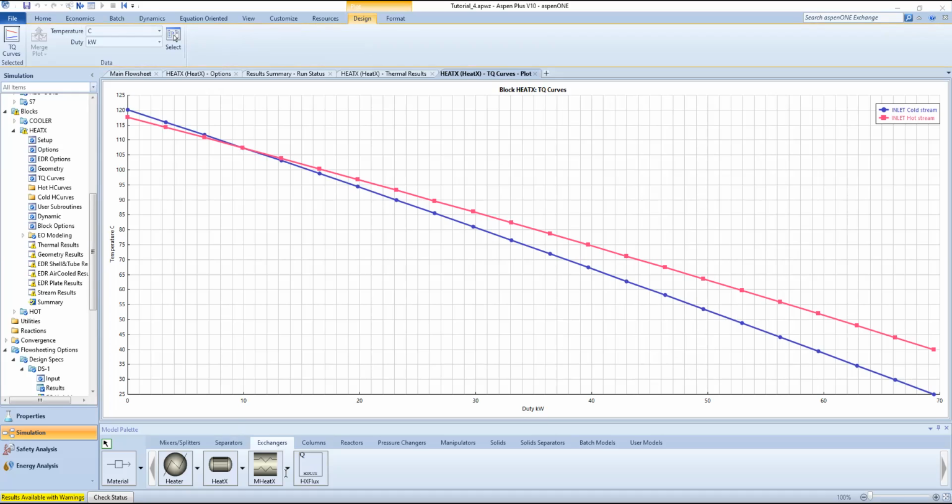So question number 5 in the tutorial is asking at what temperature in degrees Celsius the temperature crossover occurs. When you plot it, you can see exactly the point of crossover here. And it's 107 degrees Celsius. These results indicate we require a larger flow rate of water to meet the desired butanol outlet temperature. And this is what we did last time.